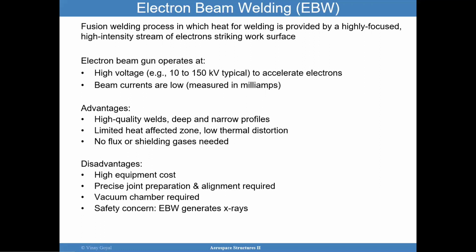The advantages: you have a high quality weld, with deep and narrow profiles. It does limit the heat affected zone, and you have low thermal distortion. There's no flux or shielding gases needed. The disadvantage, again, is the cost. This kind of technology can emit X-rays, which could be a health concern, and a vacuum chamber is required. You also need a lot of preparation and aligning of the system to make this work.